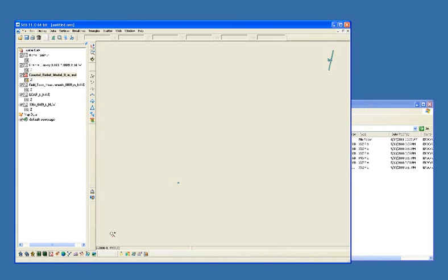If it shows up and you get this relationship where one is in the lower left and one's in the upper right, normally what that means to me is that it's a difference of horizontal being in feet as opposed to horizontal being in meters. So it's a factor of almost 3 in both the X and the Y direction, so it puts it in this type of situation.